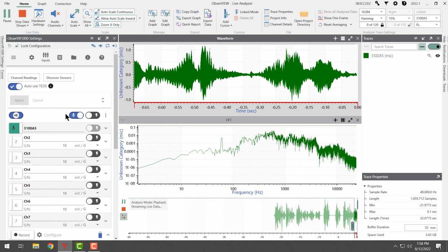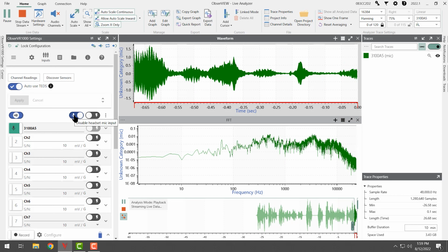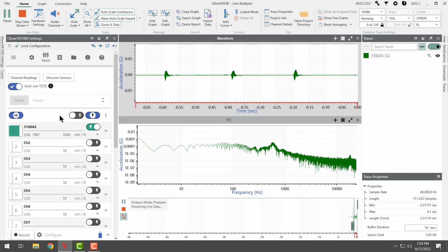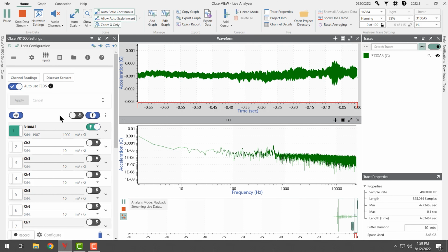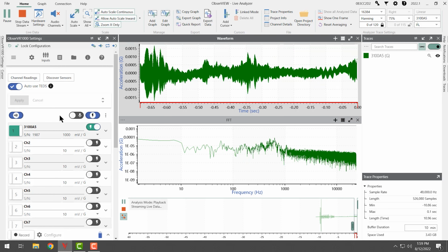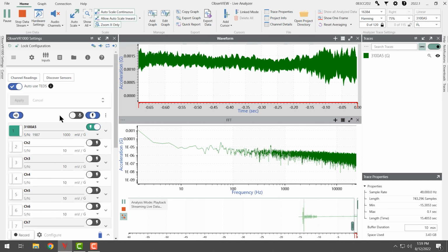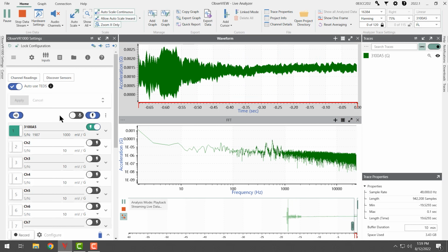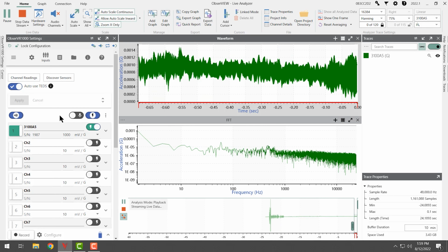So what I'm going to do is reverse my process a minute. I'm going to turn off that toggle switch and unplug my headset mic. And you see the acceleration is back on the screen. And what we need to do is, when we plug the microphone in, it is writing to that channel 1 where I have my accelerometer currently attached. So that acceleration data is going to be masked or taken over by the microphone.